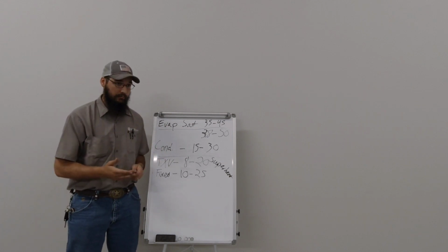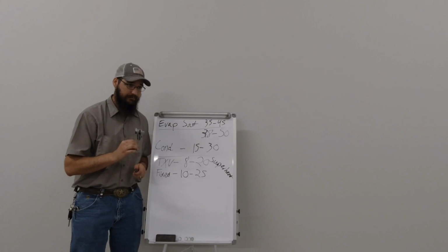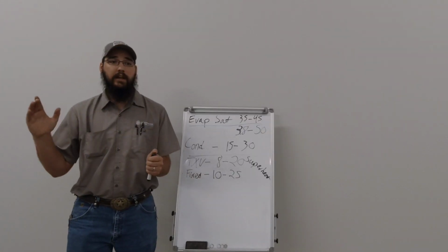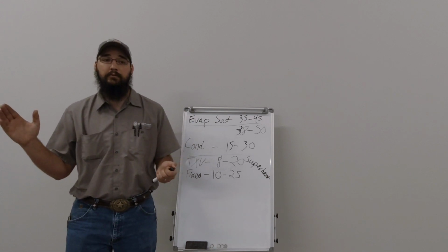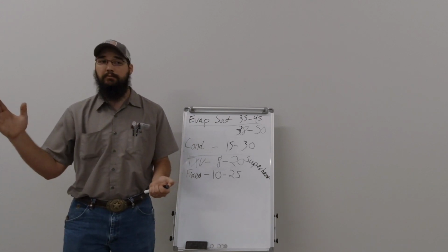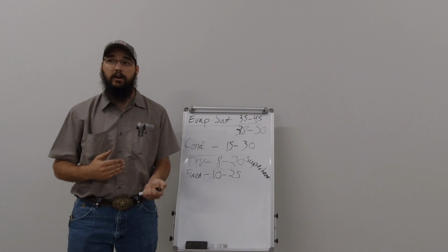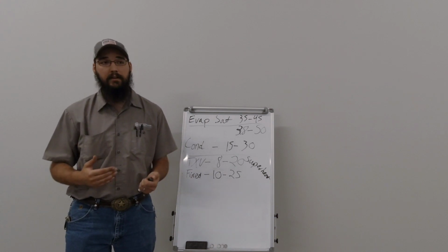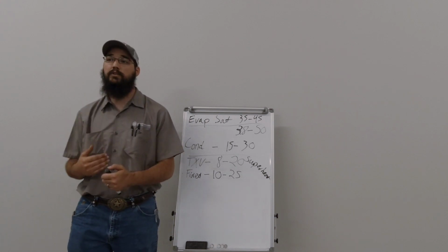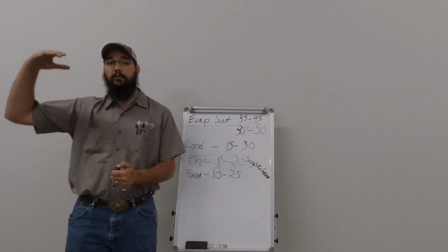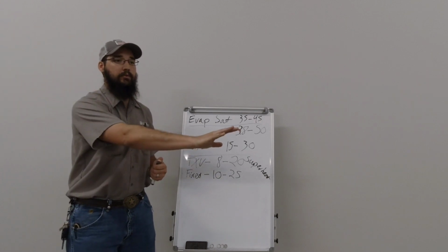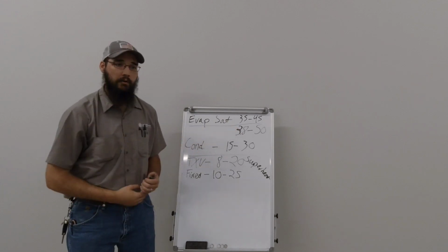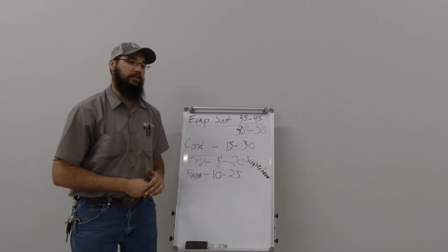So on a three compressor circuit, you're going to get completely different readings as that stages up. Now granted, you have to have enough load to support that to begin with. If you try to run all three compressors with not enough load on it, you're probably going to start flooding back, just because it's trying to force too much cooling on the system. It's forcing the head pressure to run at too great a pressure, and it's forcing it through into the evaporator, and it's overpowering the metering devices.